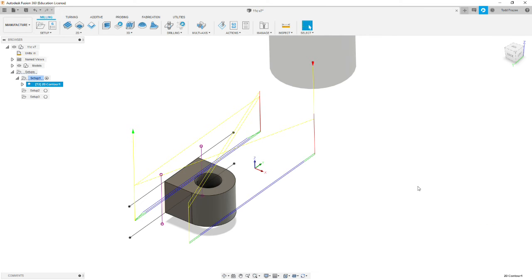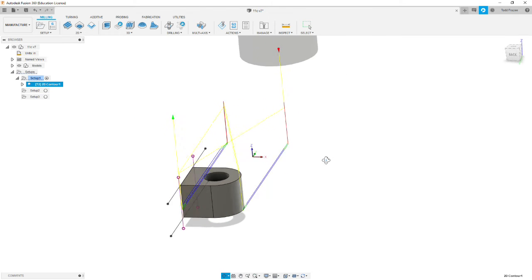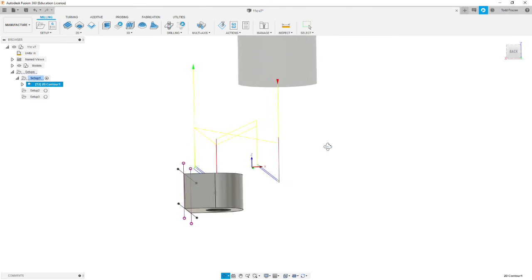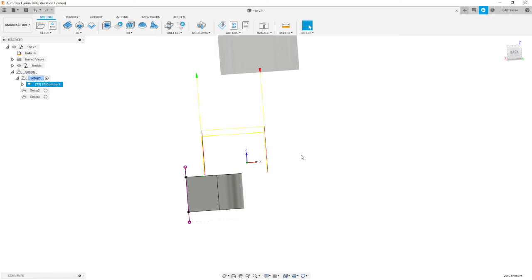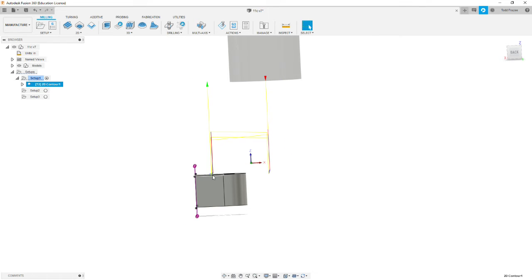And you should get several passes that move from near the screen and approach the line. And remember, this is the center line of the tool, so when you see this tool path, the edge of the tool is actually cutting past over here, and that's to give clearance for our 1/8 inch end mill.